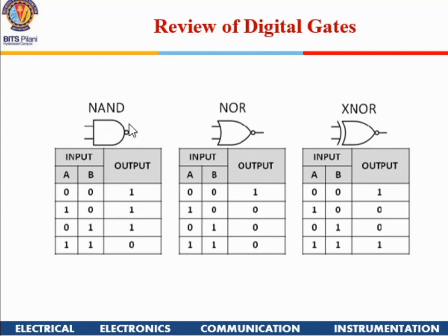This is a NAND gate. A NAND gate is nothing but an inversion of an AND gate. You might ask, sir, why NAND and NOR, and not only AND and OR? Because to physically realize a gate, whether in TTL logic or CMOS logic, you can always implement NAND and NOR functions, and you have to put an inverter to get an AND function. So that is why we always stress NAND and NOR.